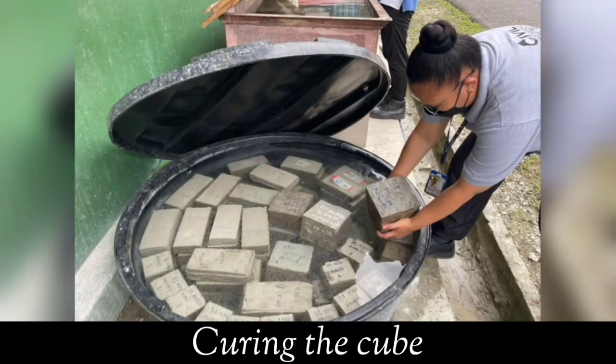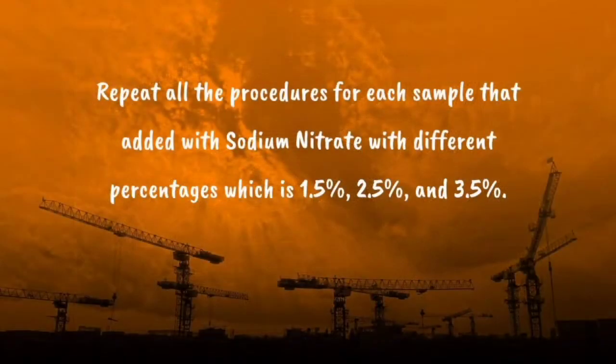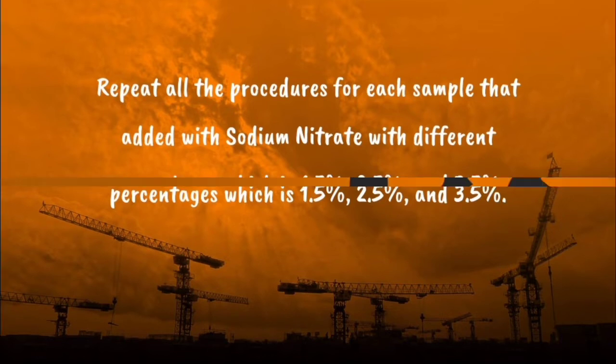All the test specimens are stored in moist air for 24 hours, and after this period, the specimens are marked and removed from the molds and kept submerged in clear fresh water until taken out prior to the test. The water for curing should be tested every 7 days, and the temperature of the water must be at 27 degrees Celsius and below. Repeat all the procedures for each sample that is added with sodium nitrate at different percentages, which are 1.5%, 2.5% and 3.5%.